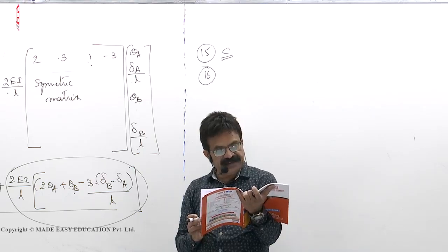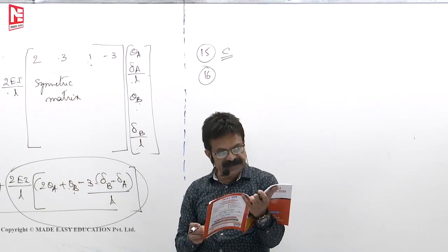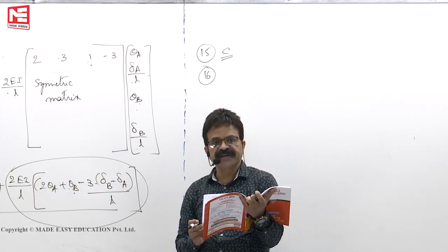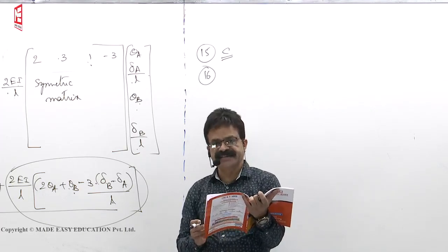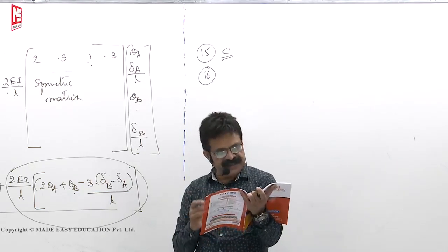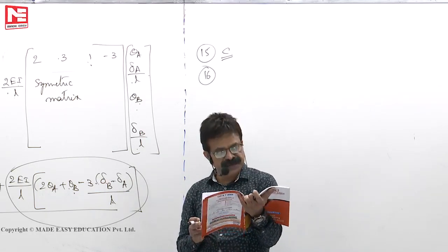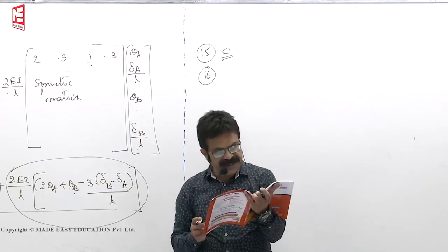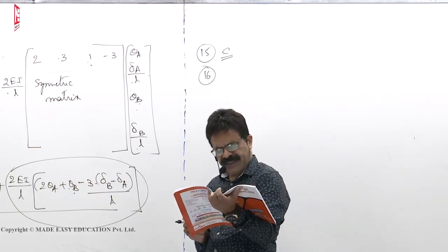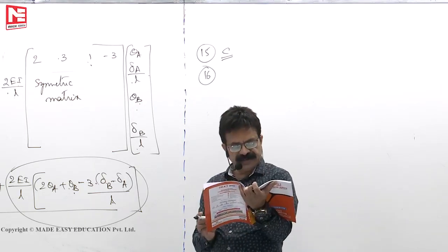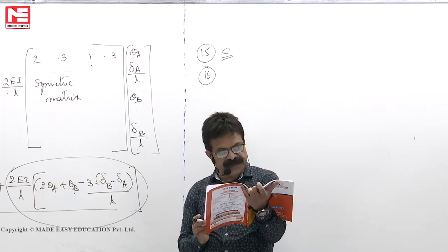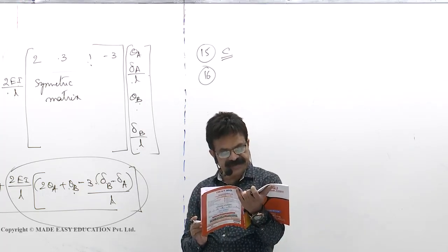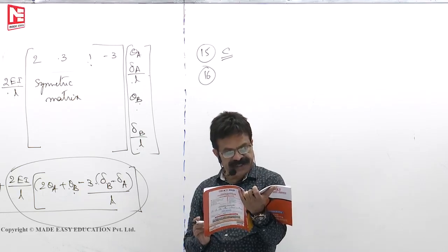That we cannot tell because it depends on ds and dk, the simultaneous equations to be solved. Very much smaller you cannot tell. If ds is more than dk, say, then the number of simultaneous equations in the flexibility method will be more. So B is wrong. In flexibility matrix, equations of equilibrium will inevitably be unsymmetric and less sparsely populated, while the stiffness matrix is always symmetric and sparsely populated.